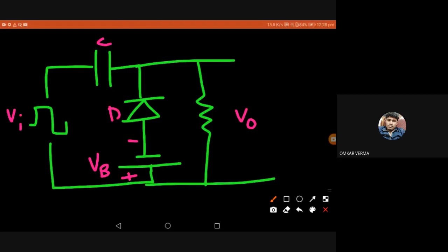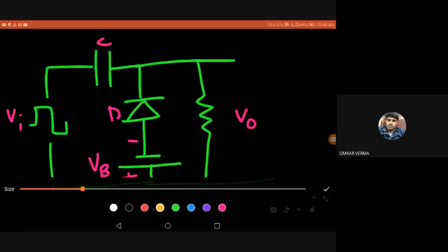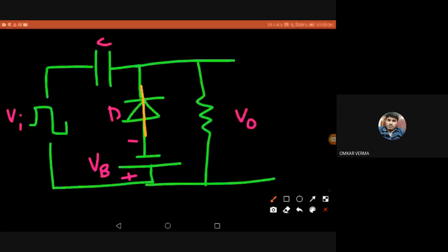Now we can see here, the diode will be on when the anode is positive and this side is negative. So that is the input cycle you have to assume, analyze that cycle as the starting point. How much? 10 volts. So you take 10 volt in the input. This will be our input cycle, the negative cycle, which forward biases the diode. So we'll start analyzing with that cycle. Now we have the battery voltage VB. Say for example, VB is 4 volt, like the previous example.